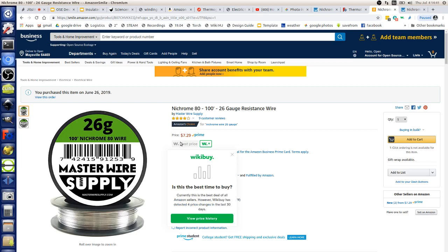That's great, because you actually cannot get a 500 watt heated bed off the shelf. I've looked for 8x8s, I couldn't find one. They have larger ones that are 500 watts, but 500 watts for a small heat bed, that's a lot. It's kind of getting industrial on you here. And then we're running at 120 volts, so we have a 120 volt heat bed with a ground fault circuit interrupter for a safety feature.